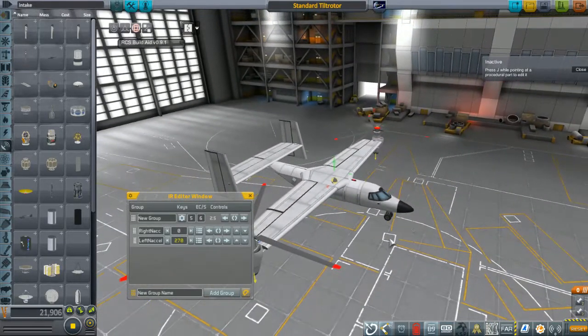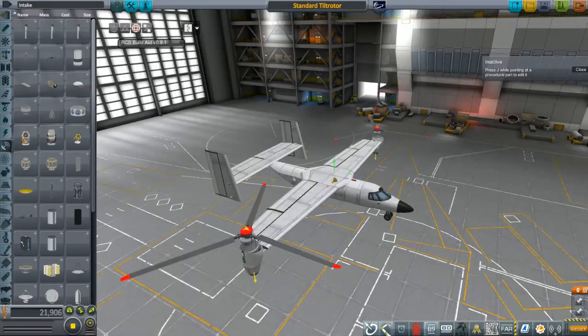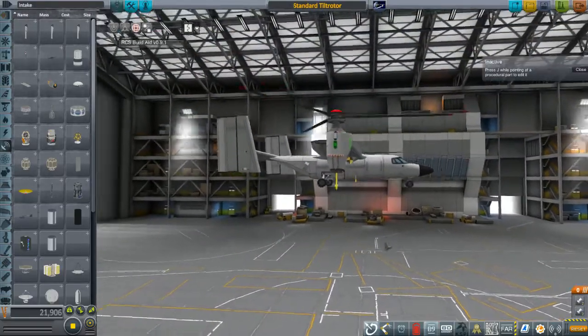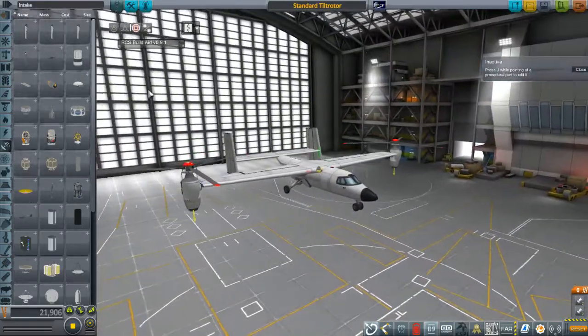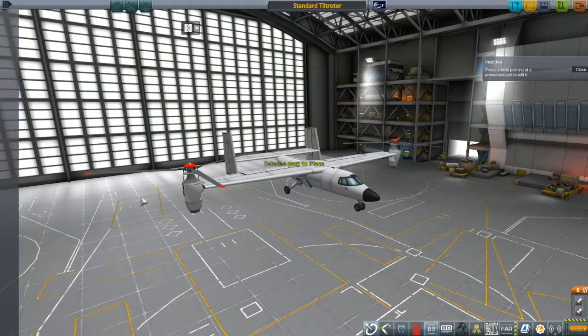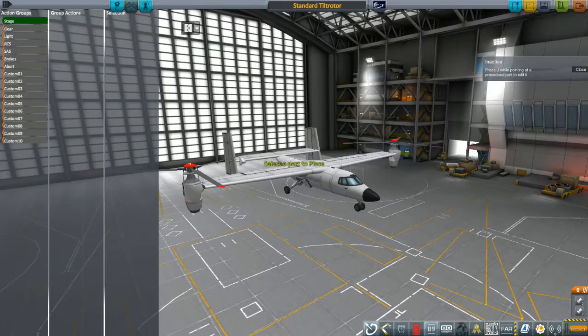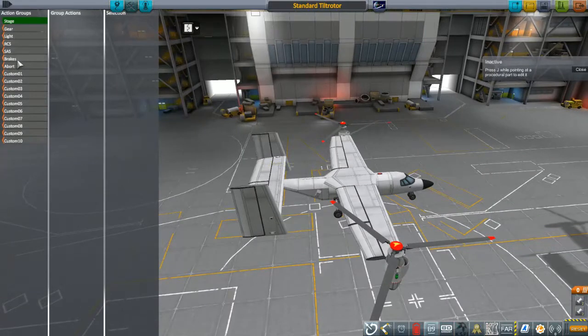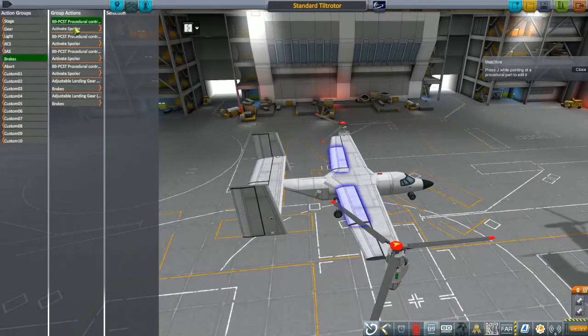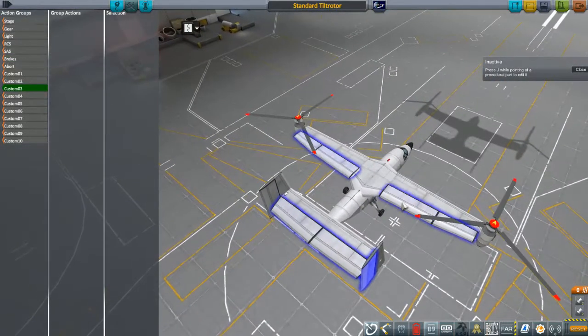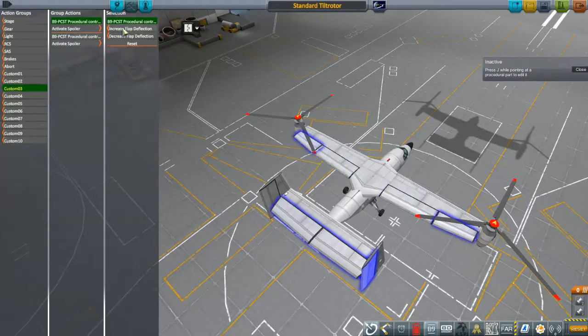And now for the next part of this operation. We pretty much have the tilt rotor set up how we want it, gear set. Now we have to actually configure all the controls. One of the first things I'm going to do is get rid of the spoiler activation that's attached to the brakes. We don't want those attached to the brakes. We want those in an individual command elsewhere. And both sets of spoilers I have to remember to set.